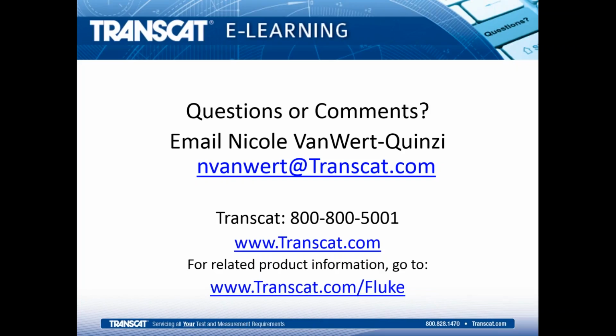Okay, great. Here's another one. How do you know the dry block calibrator temperature is stable enough to take a reading? Okay, so if you have one of the field metrology wells, the stability indicator will tell you when it's met your criteria. So let's say you wanted it to be within 1/100th of a degree, then you could set that as your criteria, and it will light up when it's met that criteria over a specified amount of time, such as 5 minutes.